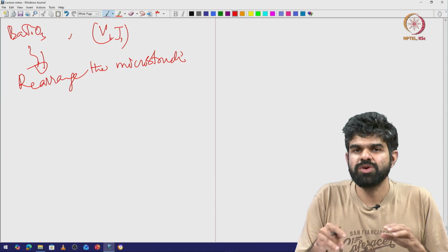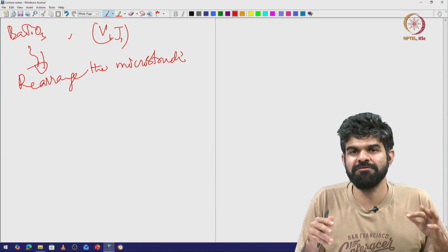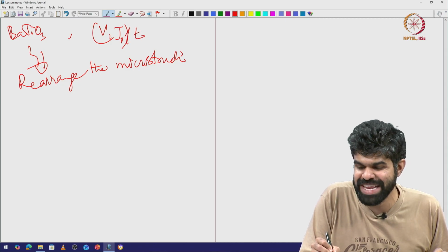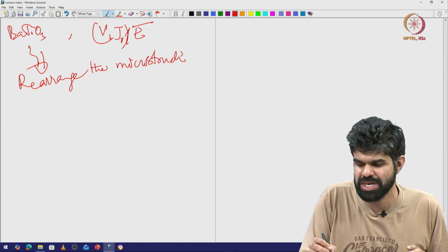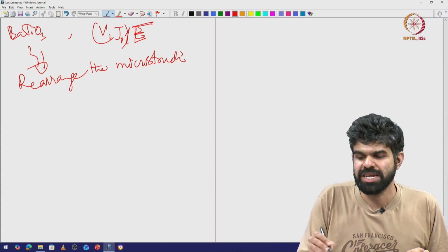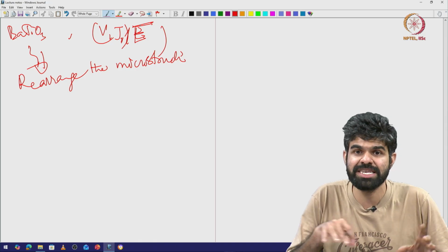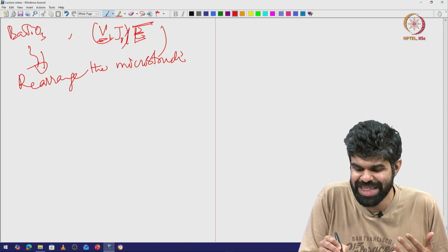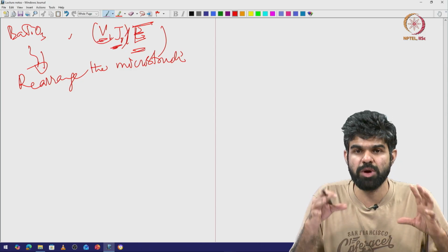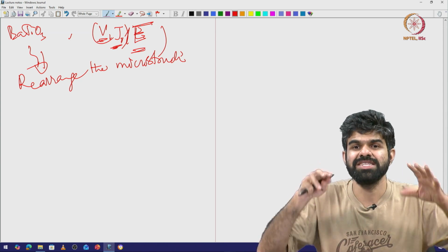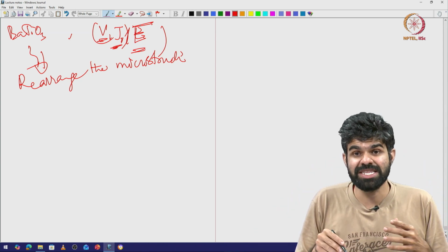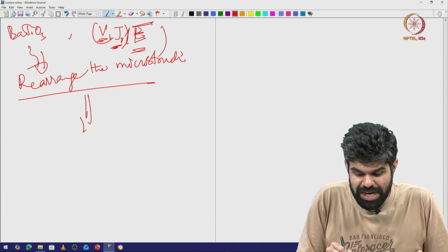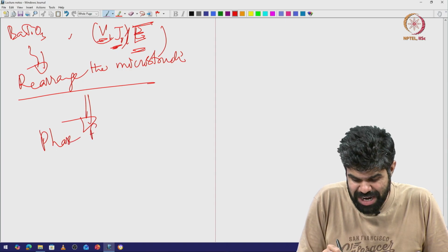Okay, you need V and T, but for barium titanate if you are interested in polarization and other things, you should also fix some conditions in terms of the electrostatic energies, right. So that is the electric field or voltage, right. So once I fix all these things and I ask it to reorganize itself, this is the mechanical, this is the thermal, this is the electrostatic boundary conditions. I fix them, and then I ask it to rearrange itself, I will come up with some interesting microstructures, right? And this can be calculated using the purview of what is called phase field modeling.